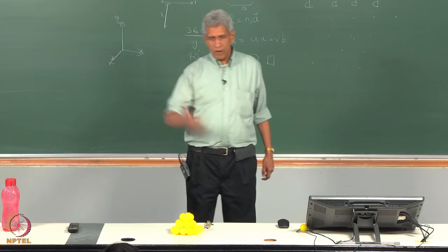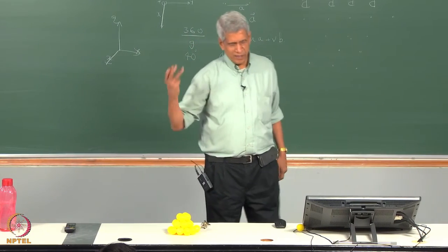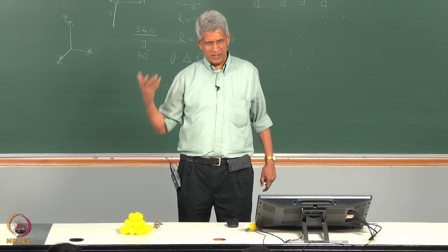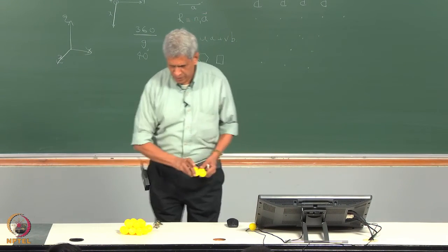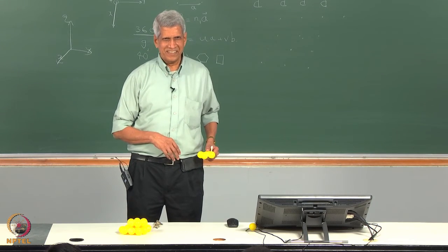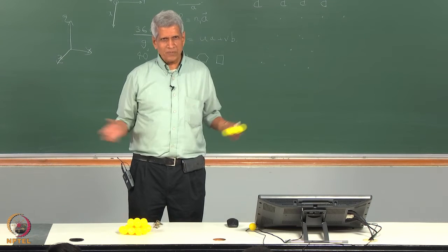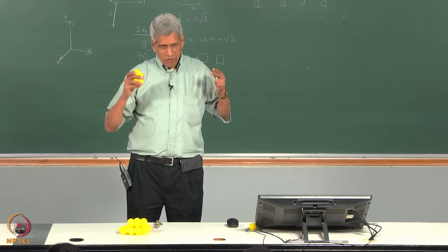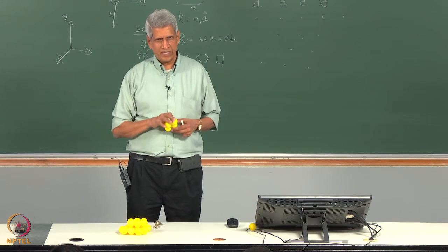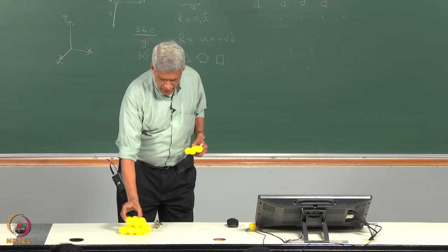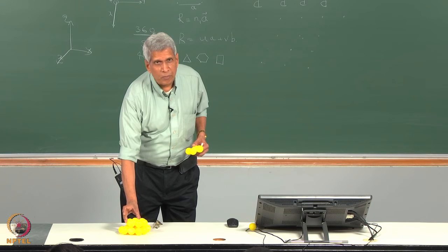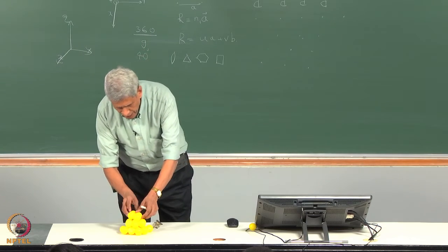Depending upon the height at which I do it, I can create simple cubic, BCC, FCC, and if I keep this one just on top of each other, it is a simple hexagonal lattice, correct. So various types of lattices can be made from these two-dimensional lattices by arranging one on top of each other. Here what I have done is I have kept one on top of the other over a symmetry point. I can do it in another way.